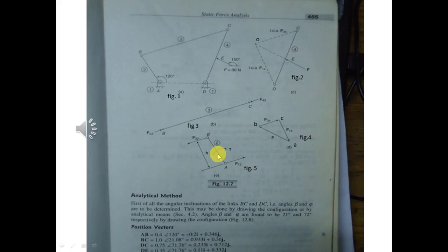And remember that this height h is not the length of the link. Many students get confused. Usually they will take the height h equal to the length L, they assume. It's totally wrong. You are supposed to take the distance between the line of action of F32 and the line of action of F12. Thus you will be able to determine the input torque value. But we also know that the input torque has to be equal and opposite to this couple. So T will be a positive value. So minus F32 into h is equal to 47.8, this is what was found out from here.